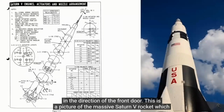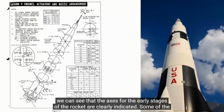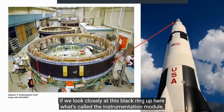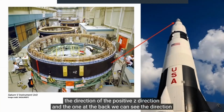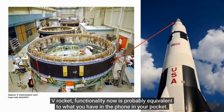This is a picture of the massive Saturn V rocket which got the astronauts to the moon and back, and again if we look at the documentation carefully we can see that the axes for the various stages of the rocket are clearly indicated. Some of the coordinate frame conventions are actually painted on the outside of the rocket. If we look closely at this black ring up here, what's called the instrumentation module, which in the flesh is actually quite a massive device, we can see quite clearly painted the direction of the positive Z direction, and the one at the back we can see the direction of its negative Y axis. This module is effectively the inertial measurement unit for the Saturn V rocket. Its functionality now is probably equivalent to what you have in the phone in your pocket.